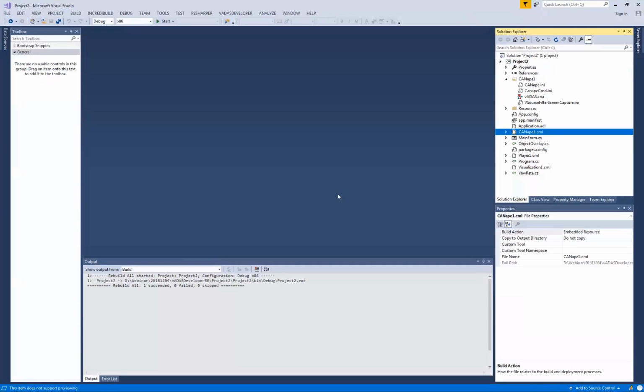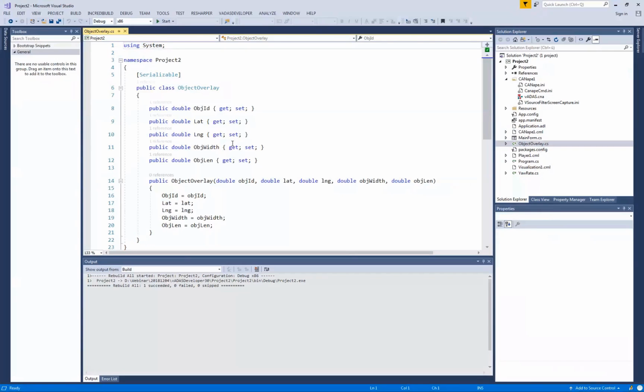Okay, now we've seen the iSignal to object converter, but there are also some other converters that we need. In our case, our radar will deliver basically 5 objects at the same time as a measurement, or let's say 6 objects or whatever. So the radar will send a message over CAN saying the next measurement is done for 6, or I recognize 6 objects. So basically, I have a number of objects, and then it will start sending me back the data of these 6 objects over CAN.